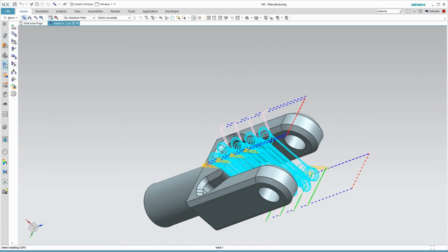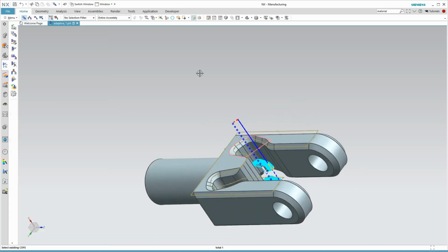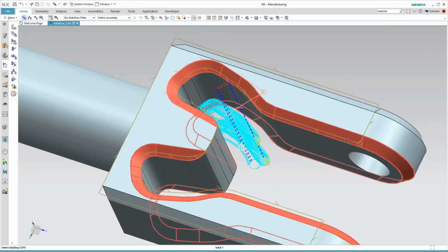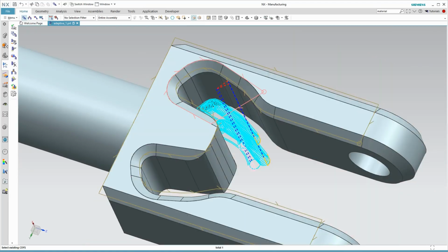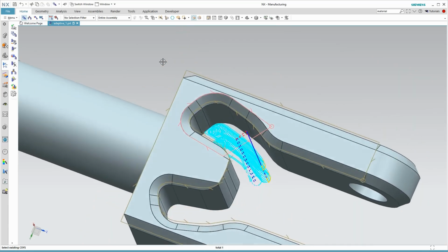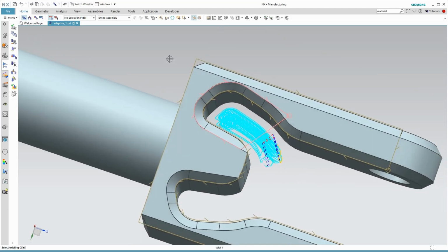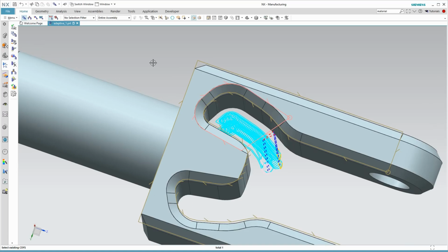Now let's look at the second operation that's shown here. We will be rotating the machine 90 degrees, and here again we see a closed shape for our part boundary, and then here is the stock boundary, so that's been manually created. And that's one of the big differences in the adaptive machining workflow: there is not a blank boundary that can be created within adaptive milling. We will be using the IPW or in-process workpiece to do that job for us automatically.